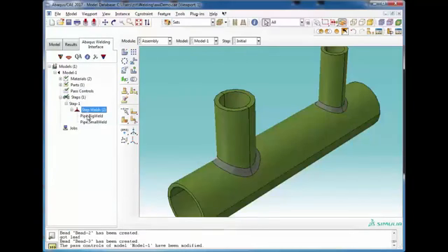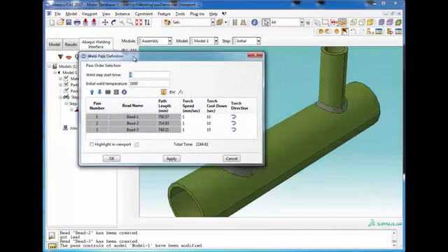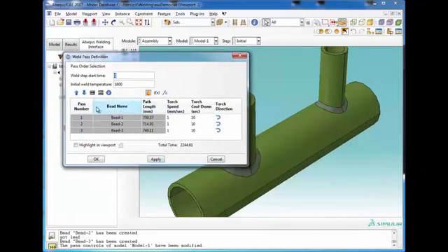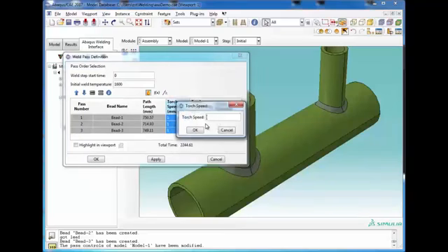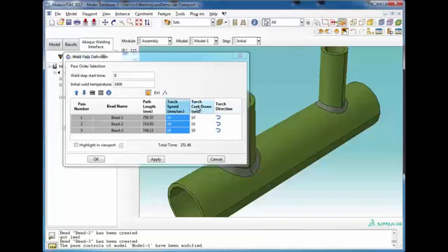So we've defined, let's just look at the big weld. For the big weld, we've got the 3 beads. The gray color represents things that you cannot modify or edit. So we have torch speed. If we want to change the torch speed, let's say to 10 millimeters per second, that's really moving. Then torch cooldown time. The plugin takes the path length, the torch speed, and the cooldown time, and calculates the total time to put this weld down.